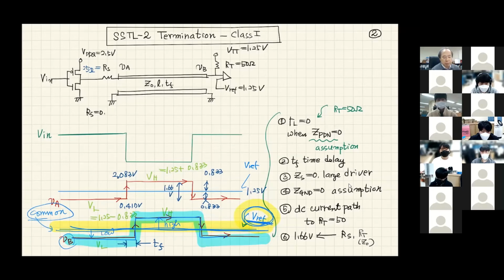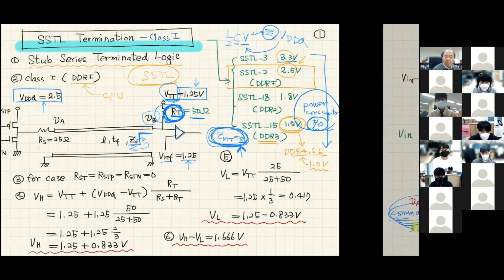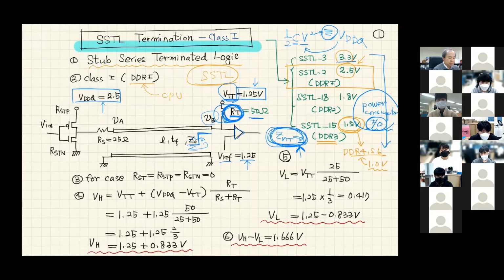In CMOS input, you have to determine whether it is a logically low or high level. And you determine that is the half voltage of 2.5 volt. And this is becoming this reference. In order to have this common mode, we need to have certain common mode. That's why we put this termination impedance attached to the power supply 1.25 volts. Let me move on continuously.